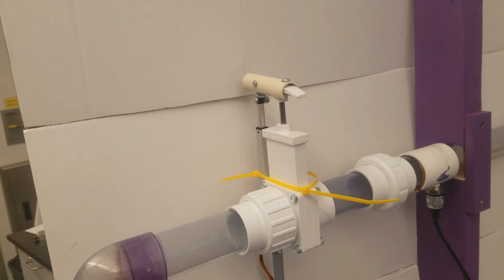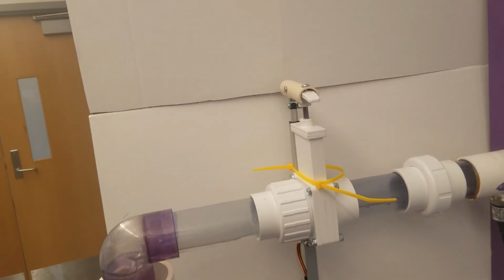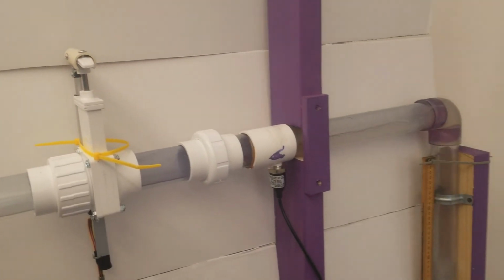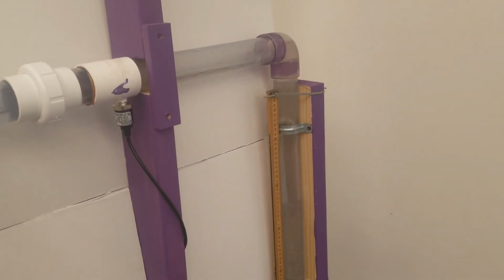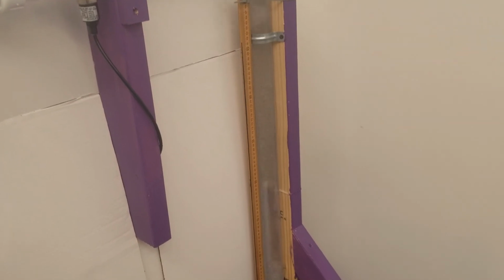You are looking at the bench model's control valve. It was implemented for future PID usage. The control valve is comprised of a 1.5-inch Schedule 40 gate valve with plunger and a 100mm linear actuator with feedback. The feedback allows our computer to see what position the valve is in.